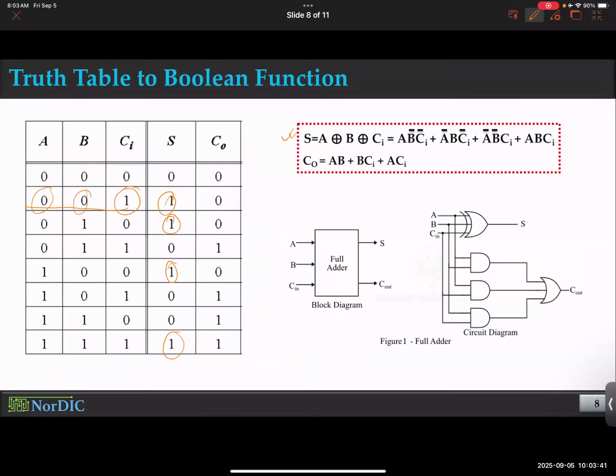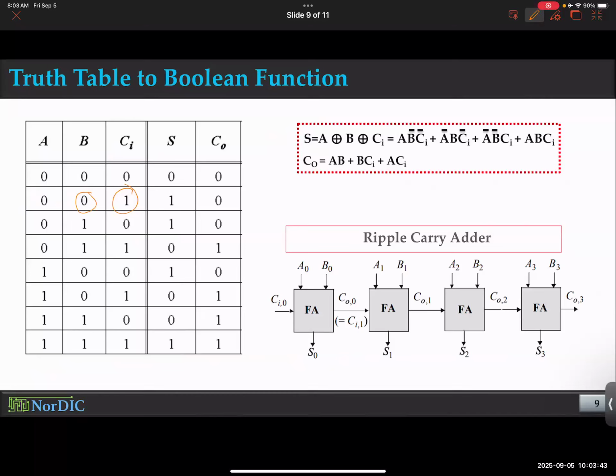It's not part of this syllabus, by the way. We basically look at it in 433. There is a project that students do. It's called ripple carry adder design. So you have an adder. The carry out of this adder is the carry in for the next step and the next step and so on. Okay, just in case you are curious, I had this figure handy. So take a look at it at home. You'll work on it in the lab. So hopefully we'll be in good shape.